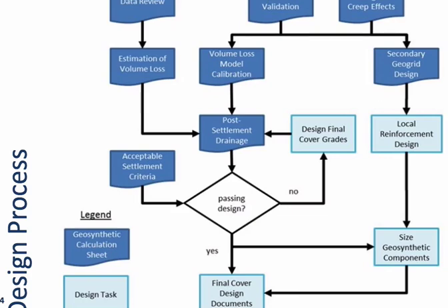We had two models. The TSS model is an acronym we came up with. It's simply a finite difference model of deformation of a thin cover system over a void in the ground. From there, we went into a more generalized volume loss model that looks at how we translate changes in volume in the ground to depressions appearing at the ground surface, trying to connect what we're doing at the macro scale to very large bench and full-scale field tests that have been conducted at other sites.